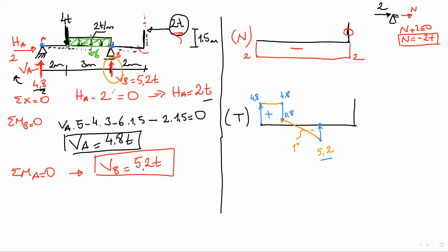Shear force at this point is 0. Now, take a look at this portion. Is there any external loading over here to change the shear force? No. That's why we go constantly at 0 level. We completed this lateral portion.